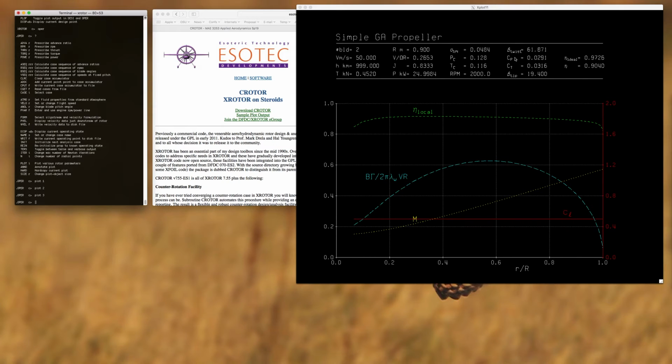You can see your power and thrust coefficients, your output thrust at the required power that you have, and then the operating RPM. This shows you that basic cross-sectional performance for your airfoil across the blade, starting at the hub location, so you're not getting any benefit of the prop out in this area.